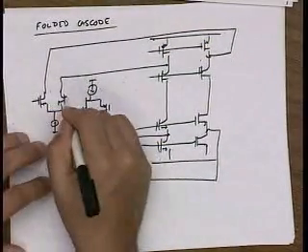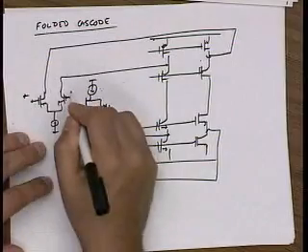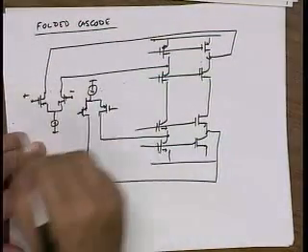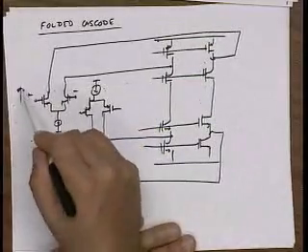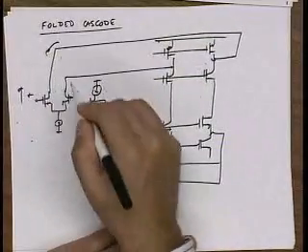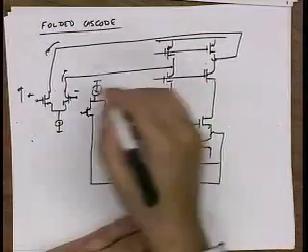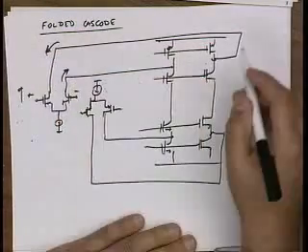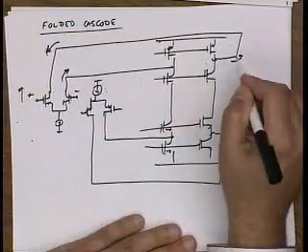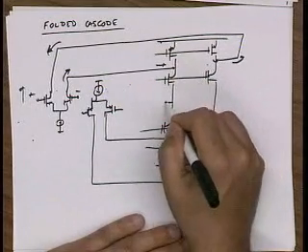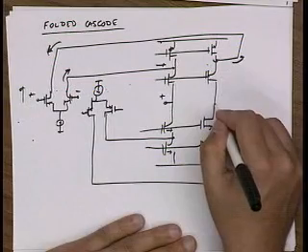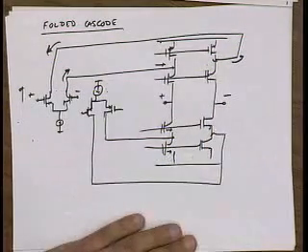And then you've got to figure out which ones are plus and minus. So if I put a plus input in here, that draws current in this direction, and so here the current is leaving, here the current is adding, so this node goes up. So this is the positive terminal. This is the negative terminal.